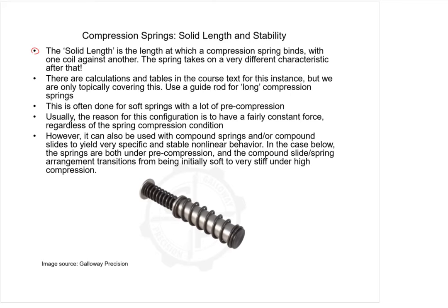We're just covering this topically, but when you have a compression spring, often you want to use a guide rod for long compression springs. That's to prevent the spring from buckling, squirming around. This is also often done for soft springs with a lot of pre-compression. The reason for that is to have a fairly constant force regardless of the spring compression condition.